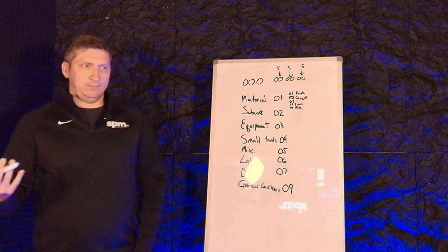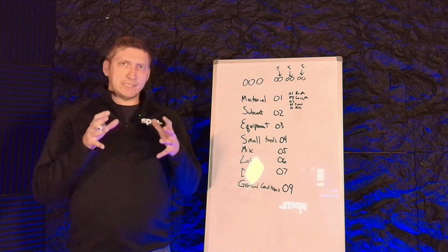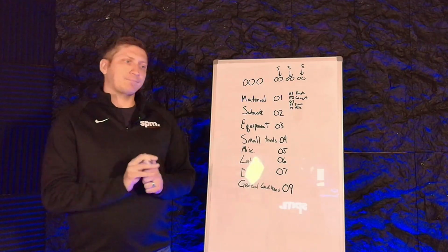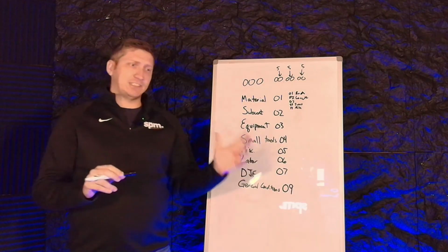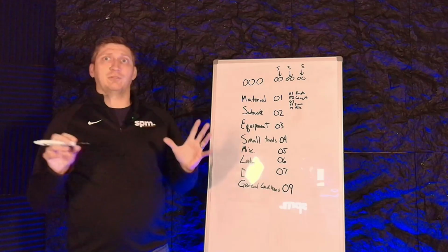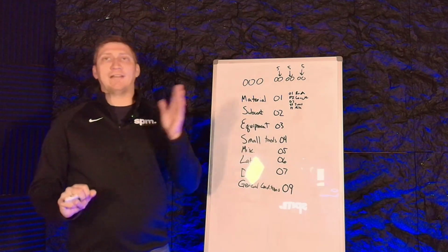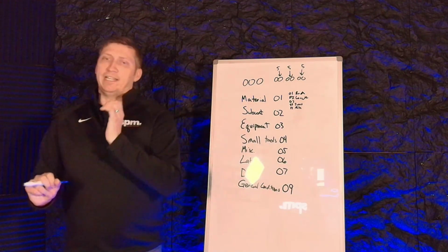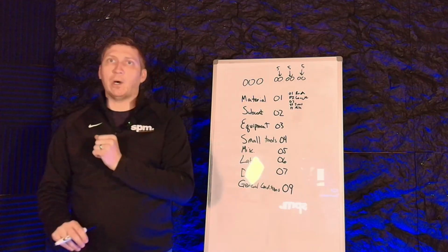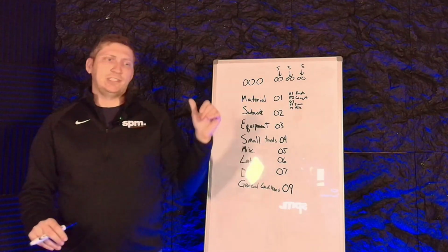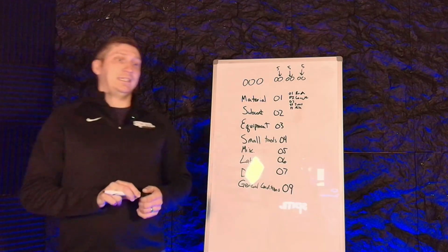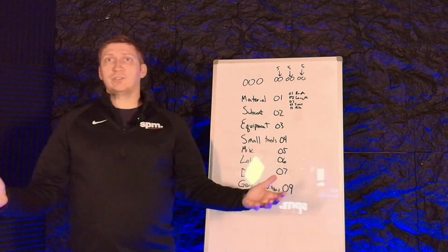06 codes, these are labor. So the way you want to build a labor cost code is per month section of work, minimum. So what that looks like for a civil contractor, I'm going to have rough grading, and then, I'm not even sure before that, I'm going to have clearing and grubbing. I'm going to have SWPPP. I'm going to have rough grading. I'm going to have concrete structures. I'm going to have retention ponds or electrical utilities or water utilities, storm sewer, whatever that is. If I'm doing concrete work, it's going to be slab on deck, building 1, whatever those are.